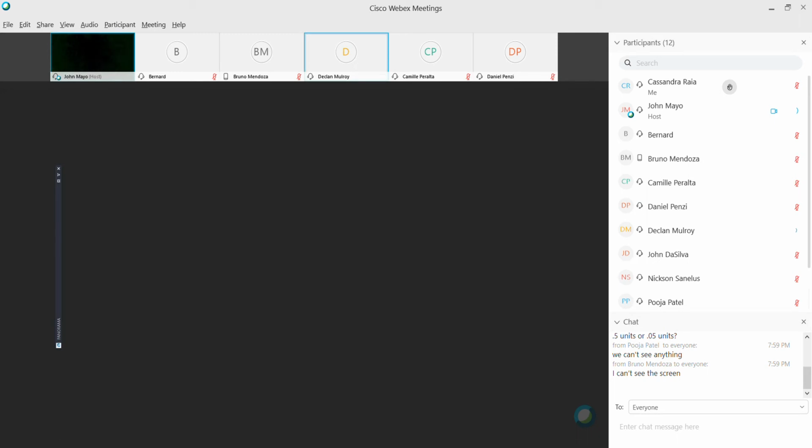And these values can be moved up or down. So if you do not want to play with your boundary, I'll get to your hand in a second. If you do not want to play with your boundary for your whole grading exercise, save it for the end. So you don't have to continually move it down to the bottom of the list when you add information to your surface.